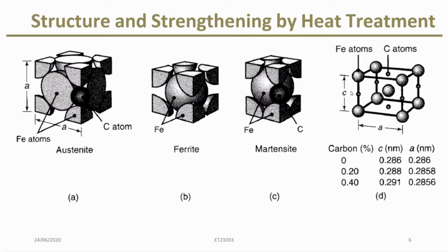The lattice shears into BCT, a strained structure. BCT means body centered tetragonal. It is a supersaturated structure that blocks dislocation motion, so hardness goes up. That's why quenched tools, dies, and wear surfaces feel glass hard.